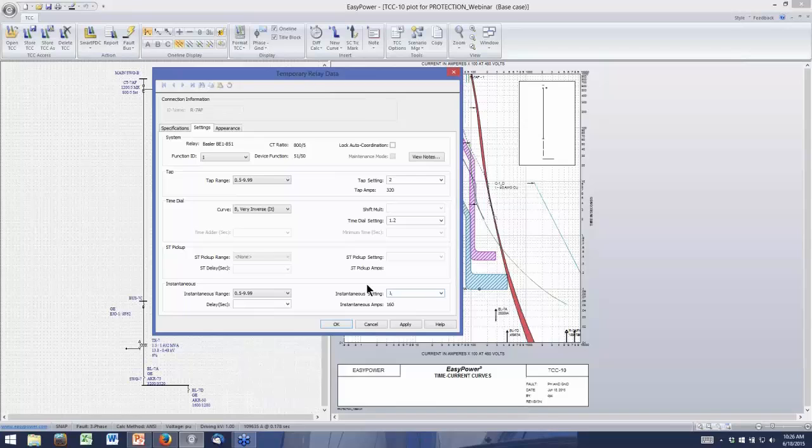Yeah, so this is in primary amps. So if I want 1100 amps, so let's say I use the symmetrical current of 1100 amps through the primary for a secondary fault. I got my calculator out, can't see that, but I got 1200, that's 1200 amps if I allow 10%, right?